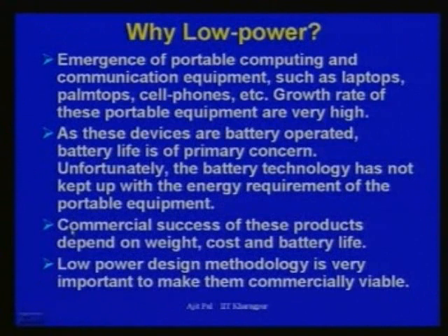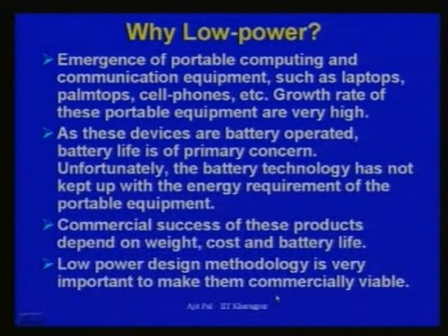In the case of portable equipment, the commercial success of these products depends on weight, cost and battery life. Whenever you go to buy a cell phone, first you will ask how small it is, whether its weight is less than 100 grams or not, and how long the battery will last. This is true for palmtops, laptops and other portable equipment. The sellability of a product depends on battery life, which in turn depends on the power consumption of the processors inside the system. So low power design methodology is important to make them commercially viable, particularly portable equipment.